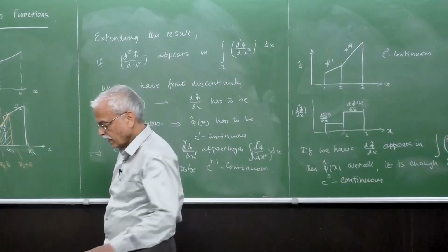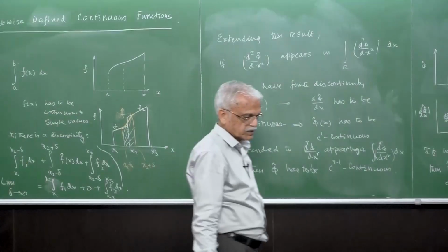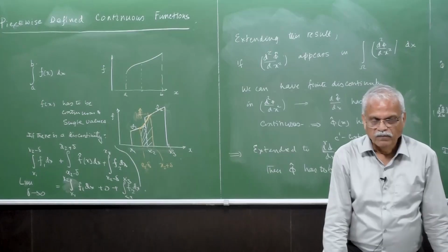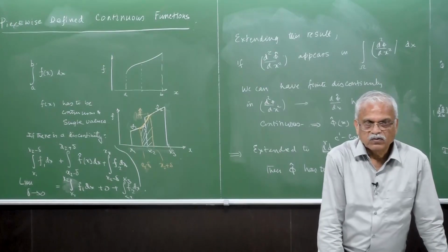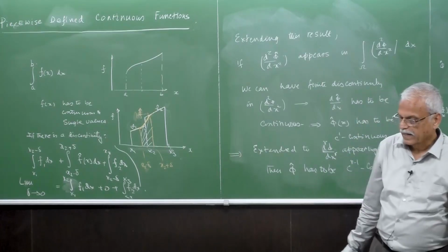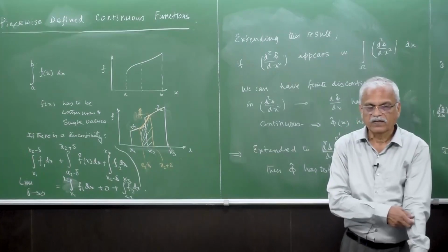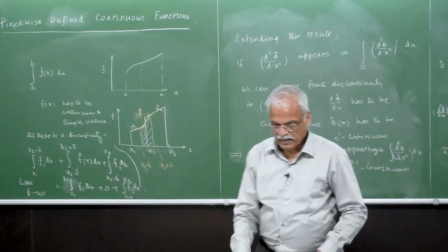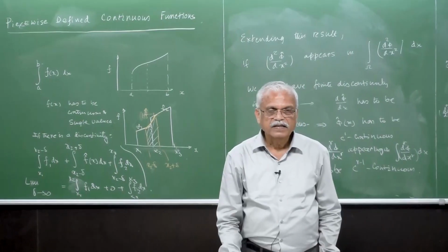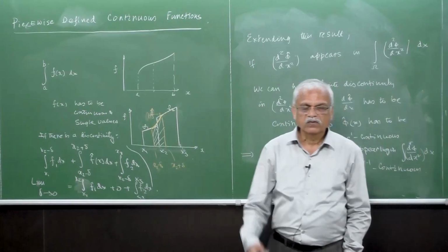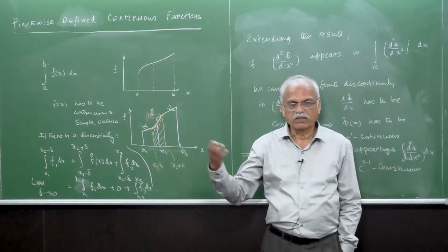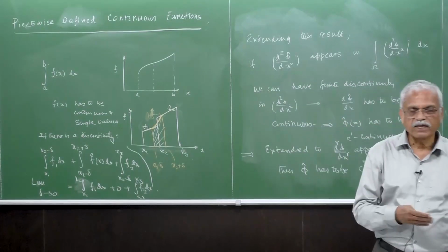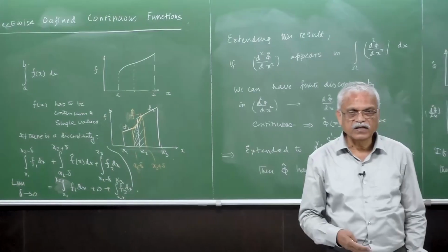Okay, so the weak form of the weighted residual statement gets a very special significance, in the sense that if you have L as a certain r-th derivative, then if you go for the weak form, that is reduced to r-1 or even further down, and the requirement on φ̂ is further reduced.